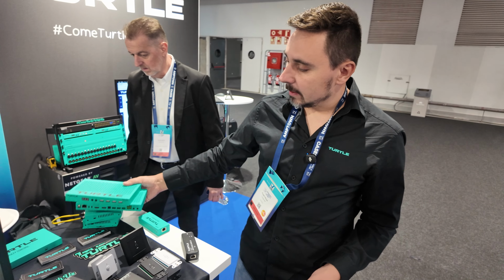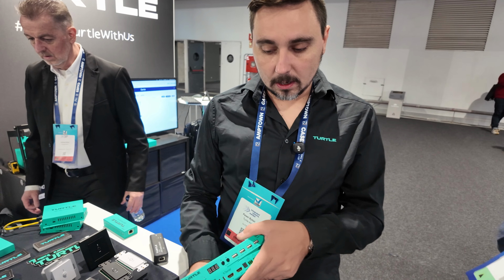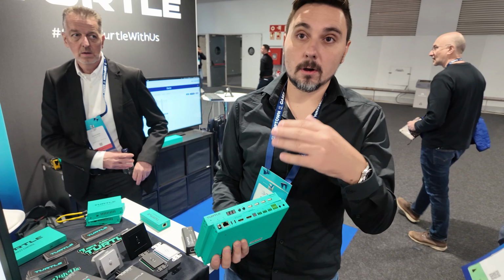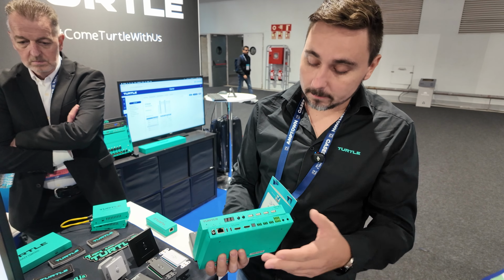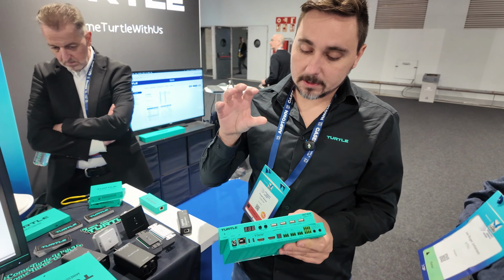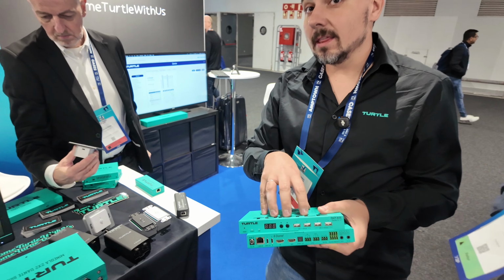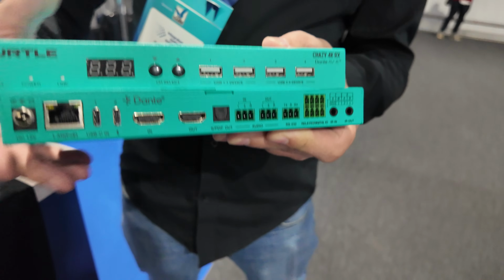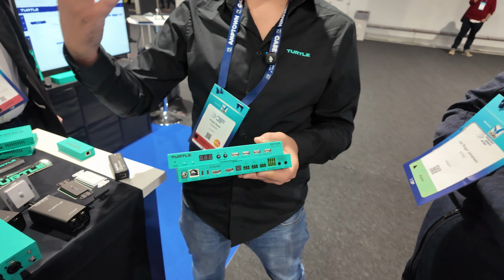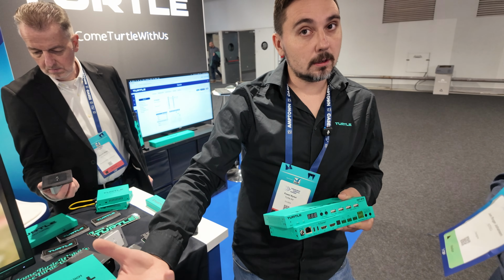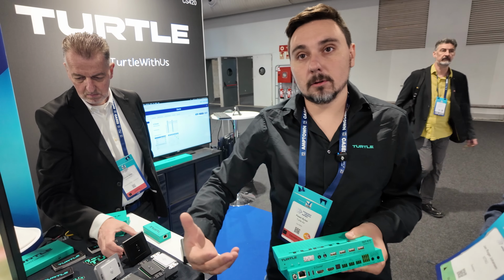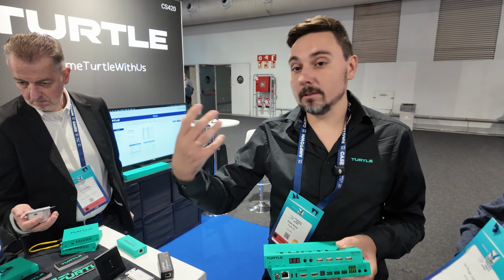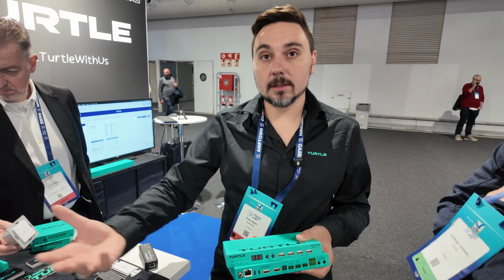And then we have our AV over IP system with Dante support. So this is a 4K 60 444 AV over IP system for Dante AV-A. So the core difference here is you can manage your AV or video system with your Dante tools. So once you put it on the network, the video channel shows up in Dante Controller. So all of the tools that you use traditionally for Dante audio management can be used now for Dante video management, and you can run your video on the same network as your Dante audio.